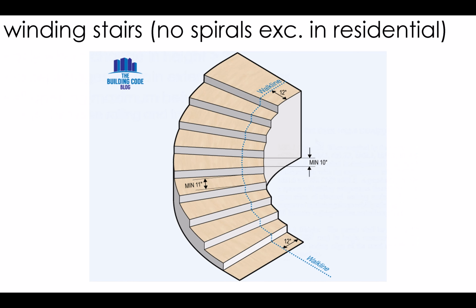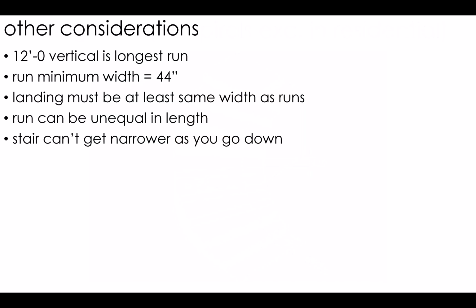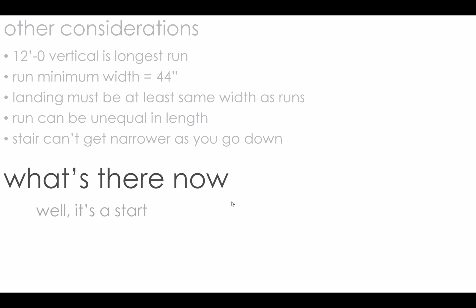Finally, people love winding stairs. It's a long and winding path that we all follow, and there are regulations about those. And you sort of end up with a minimum interior radius of about 3 feet, I believe, for these to be code compliant. Obviously, in egress stairs, no winding stairs, but these are not egress stairs. These are just public stairs. And again, there's a lot of other specific rules which you should follow.